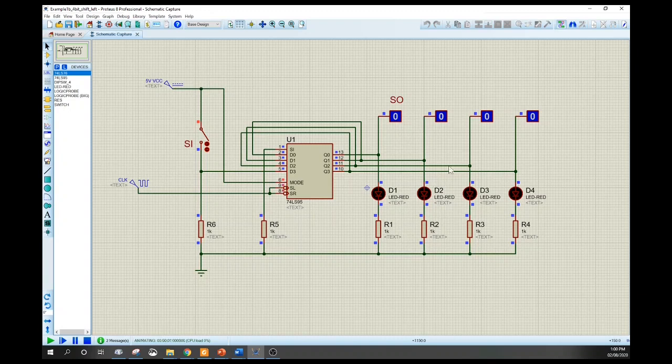So normally this is just zeros as an initial state, but in the case of registers, once you turn on your power in an actual circuit, this can have any values. Anyway, let's try to shift in some ones. So this is now shifting to the left. If we shift in zeros, shift in one again, you would see some changes in our outputs depending on the value of our shift input.